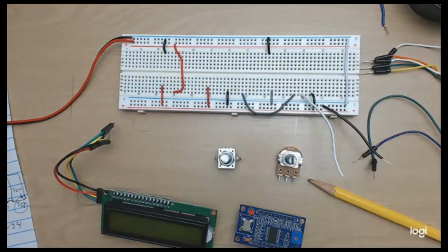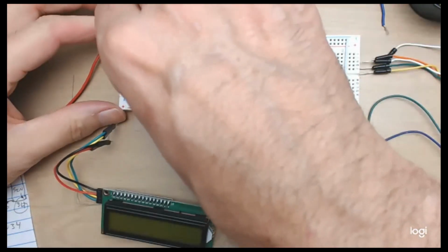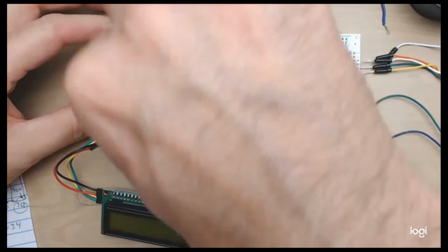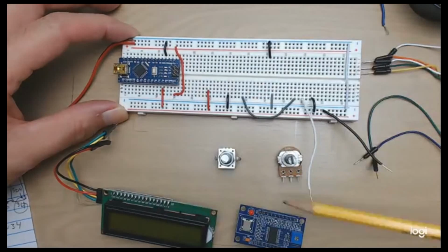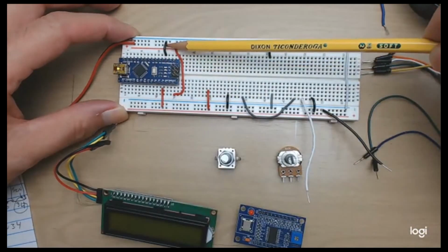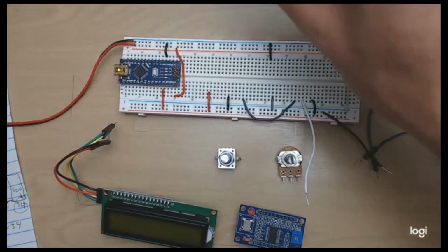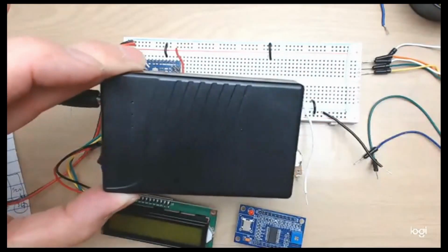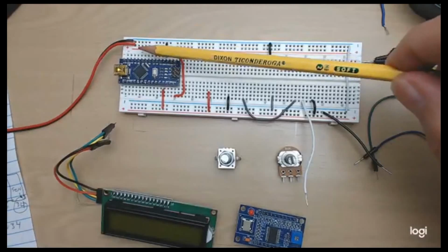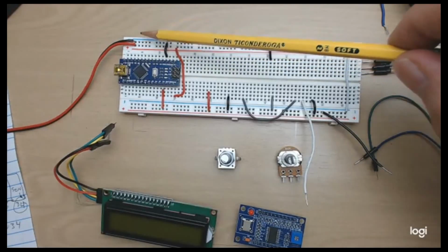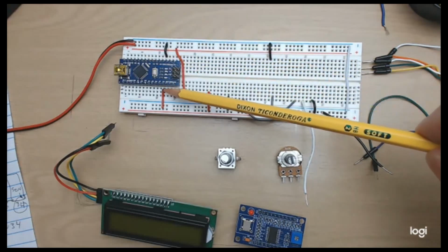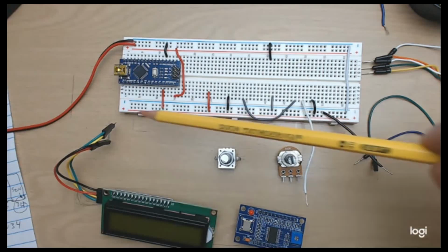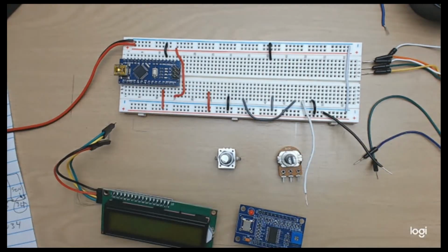First thing I'm going to do is put my glasses on. You can't see that, but I need to so I can see what I'm doing here. And I'm going to plug in the Arduino Nano into the board. So this red wire here is +5, and this black wire here is ground. I've got my power supply, which is just a 12-volt battery, coming in on the plus rail and the ground rail. And I'm connecting the ground to the Arduino, and I'm taking 5 volts out of the Arduino and putting it on this rail over here. So I have a 5-volt rail over there.